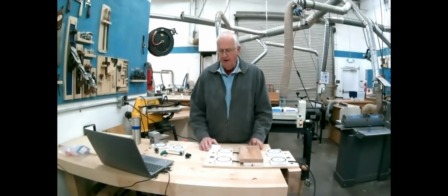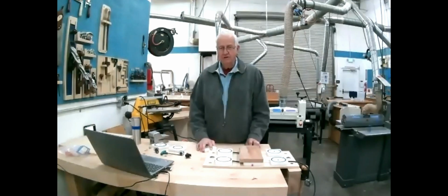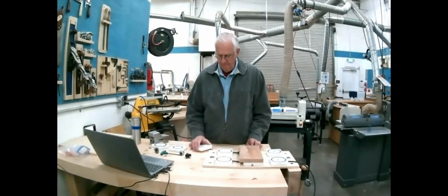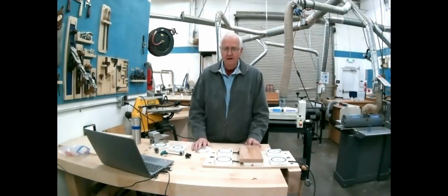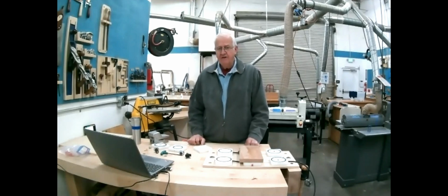But he also has some valves. His valves do not work. Don't even think of buying those. They're marginal at best. Valves as in the ball bearing depression valve that you have, or something else? The one I bought commercially has it. Yeah, they're both ball valves that have a spring behind them and pull down with the vacuum or open up when they're pushed down. But they have to have enough spring tension to overcome a good vacuum. Right. Okay. And the ones that he has are just way too weak to work with a decent vacuum system.